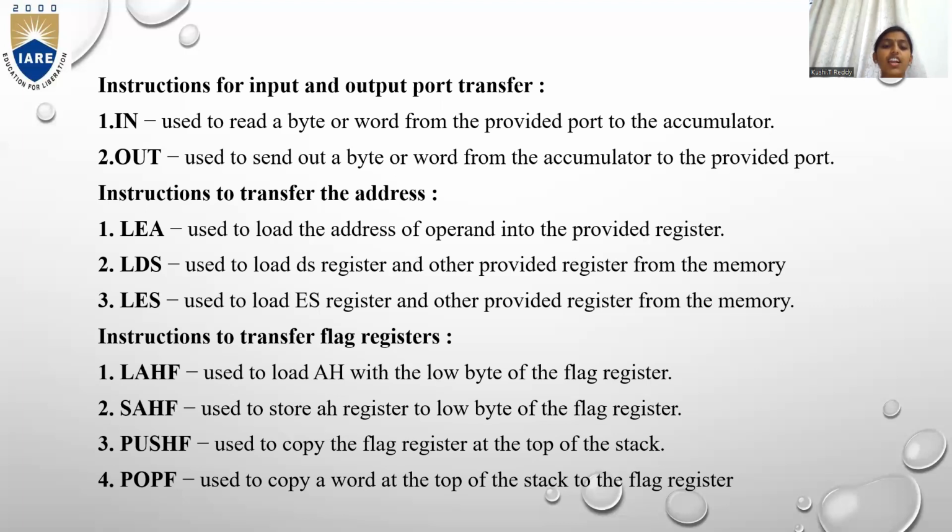Instructions to transfer flag registers. As you all know, flags are nothing but flip-flops, that is 0 or 1. LAHF is used to load AH with the low byte of the flag register. SAHF is used to store AH register to the low byte of the flag register. PUSHF is used to copy the flag register to the top of the stack. POPF is used to copy a word at the top of the stack to the flag register.